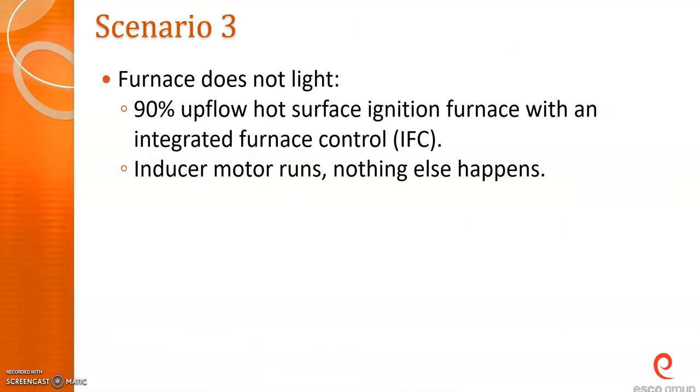Okay, we'll go through maybe one more here. So in this example, furnace does not light. So a 90% upflow furnace, that really doesn't matter. It has a hot surface ignition, so we should have a glowing igniter, and the inducer motor runs, but nothing else happens. And so that's going to probably, going through our sequence of operations, you're going to get to the